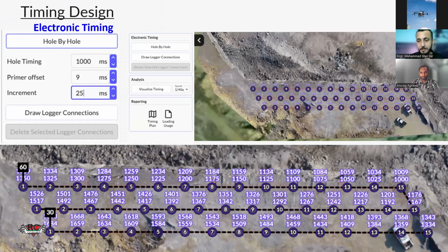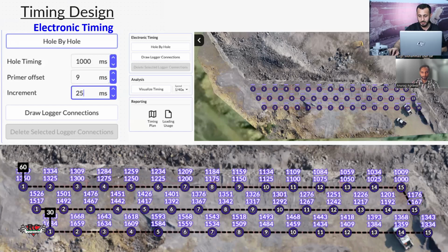So, yeah, I think I can answer this question. If you are planning on Google Earth, just mark the line which you want, marking the waypoints like a line. Every point you make on Google Earth will be a waypoint on the controller. It will be fixed coordinates. On that waypoint, the drone will be looking for the next waypoint to take a turn, like left, right, up and down, as per the requirement you give. Hopefully this will be the answer to your question. You just plan it on Google Earth and then upload the same line as a waypoint on the controller. So this will help you out.